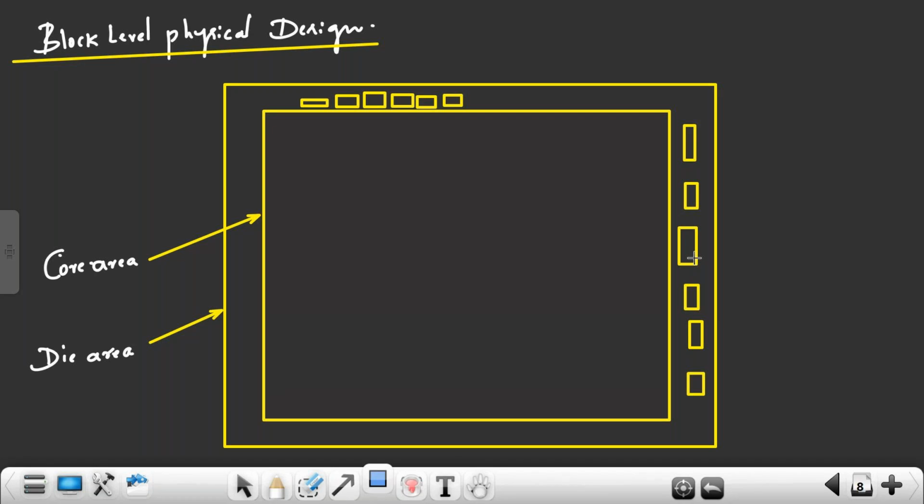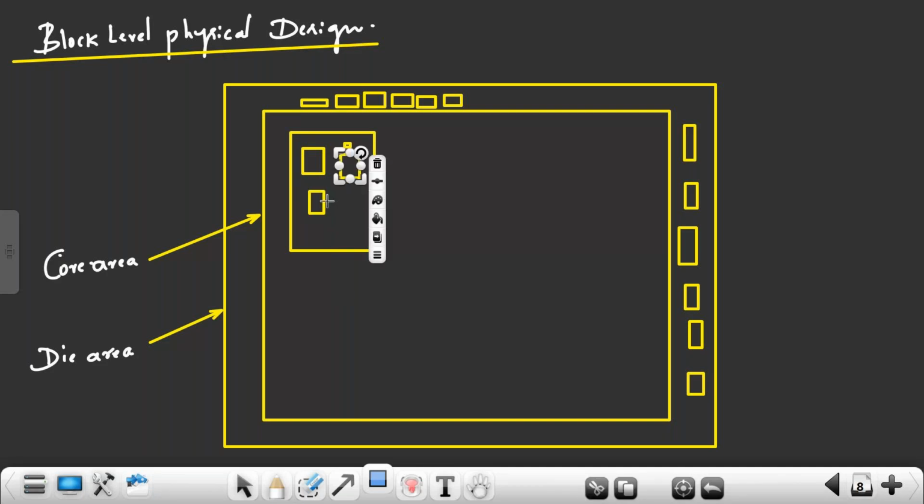So now, you will think whether directly purchasing from them is good or creating it from scratch is good. Creating from scratch means for that ALU block you have to write the Verilog code, send that to what? Synthesis. Then you have to do physical design. That ALU will be formed using different basic gates. Inside the ALU I will have different basic gates, the layout of basic gates. I have to connect them.